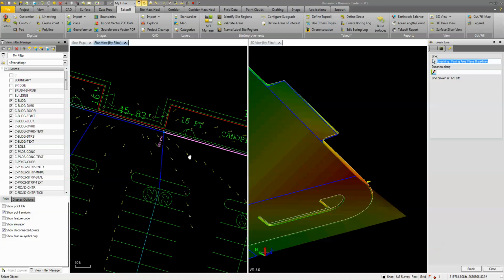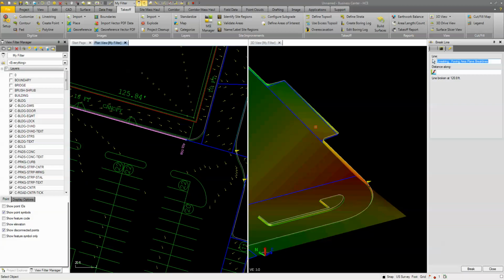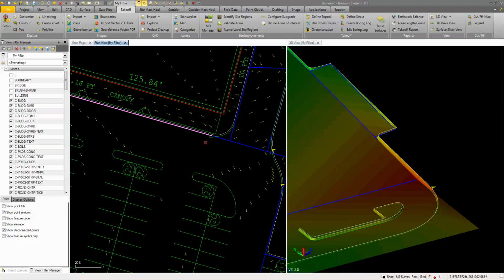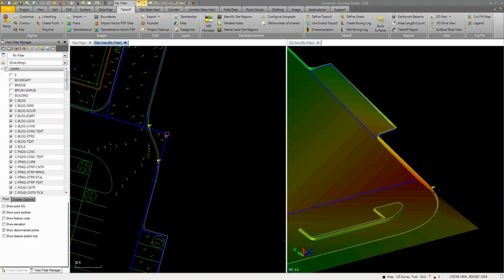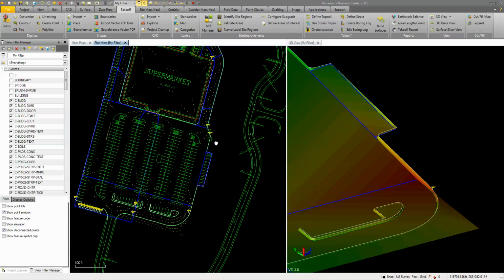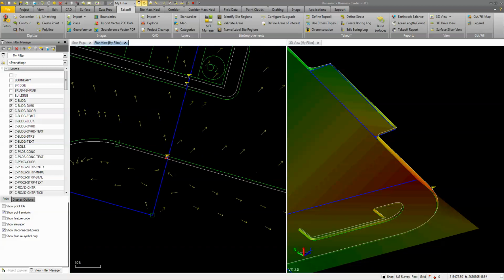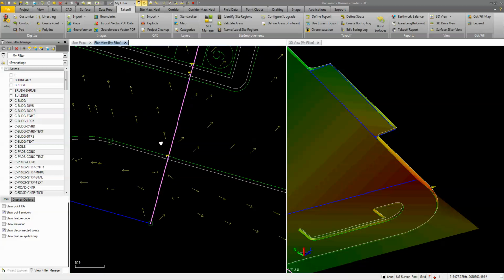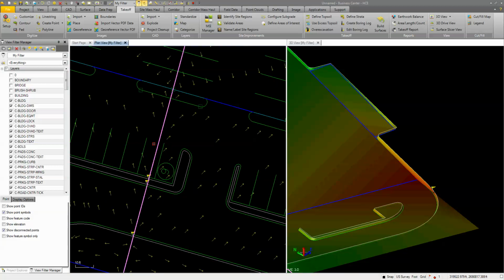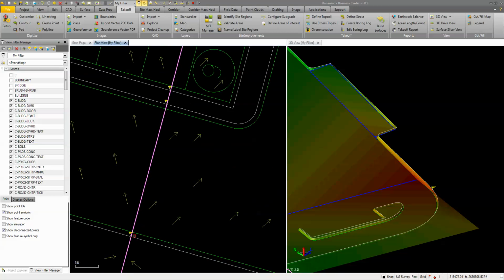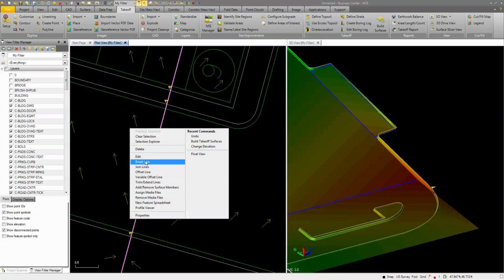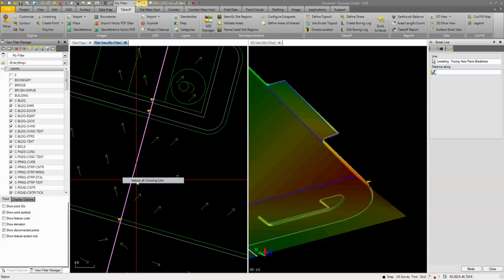And I won't need that line along the front of the building anymore. So again, let's close this. I will delete that line that's selected. I will take this line here and delete that, and do the same thing around the rest of these buildings. So this one here, I don't need this line through here actually, so let's break this, and we will break it at crossing.